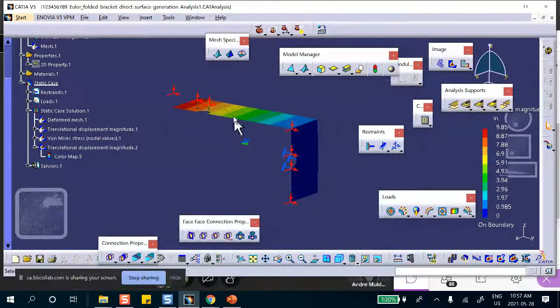If this is very thick and you put a load here, it's going to move as a rigid body. It doesn't do much bending, but it will take this guy with it. So what may stop this is not making this thicker, but maybe making that thicker.